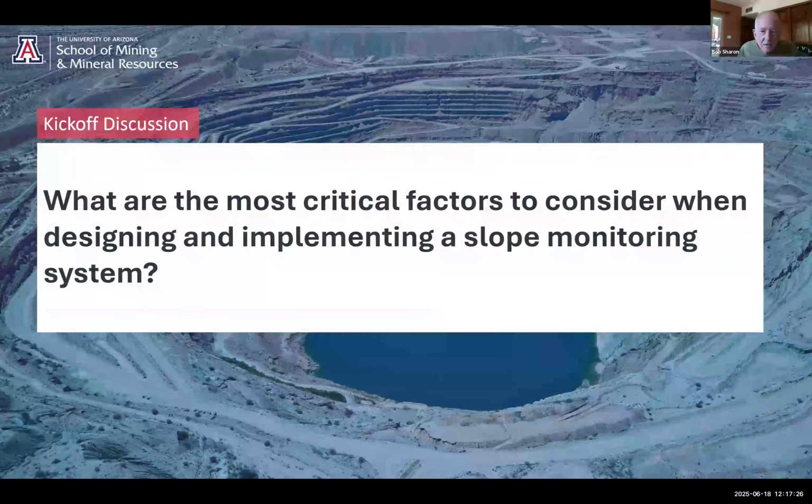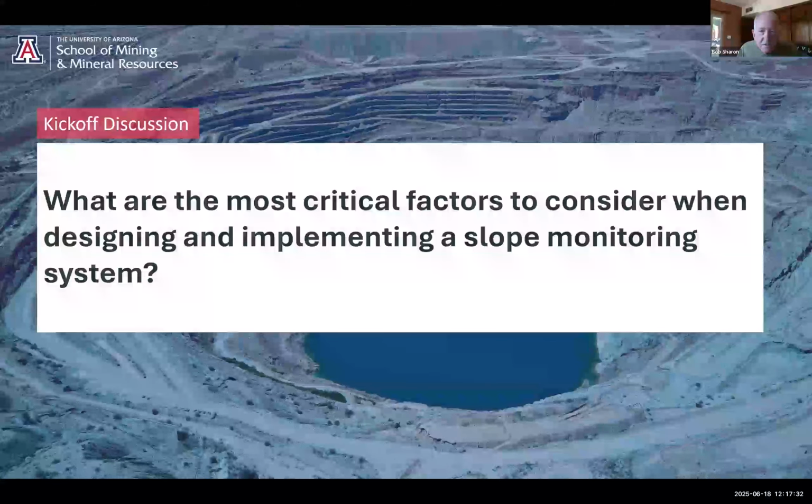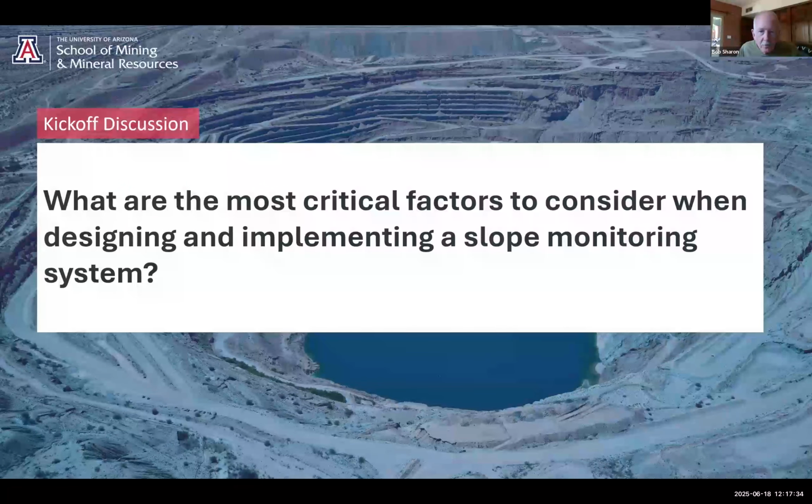Are you reaching the targets, say for dewatering and pore pressure in the slopes? So I think it's important to get a feel for what your baseline information is. And that's why you like to get your monitoring instrumentation out there early for a developing project, or to try to figure out where the gaps are and get some monitoring in there. So all of these things will ultimately fit together.